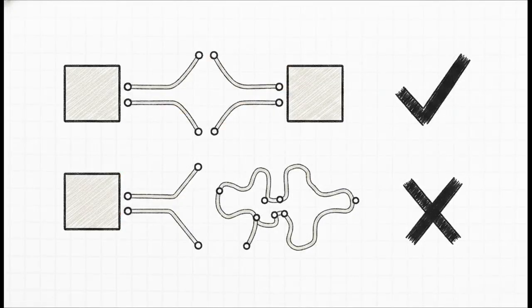Listen, routing is just as important as the transistors themselves. You have to use symmetrical routing. That means the absolute same gate metal length, the identical source resistance, the exact same drain resistance, perfectly matching via counts, and the exact same metal layer. Every single detail matters here. Remember, unequal routing changes parasitic resistance and capacitance, and that causes massive current mismatch, even when your underlying transistor geometries are perfectly drawn.